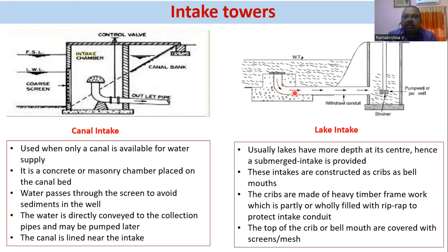So now the exit of the water is leaving into a sump. You can see here, water is collected from the lake and then through a pipe goes into a collection sump here, and from this sump you are lifting this water. So for the canal or a lake, we do not have any intake pipes. Water is directly collected, and then, depending on the levels and requirements, elevation and topography, the water can be lifted from the collection sump.